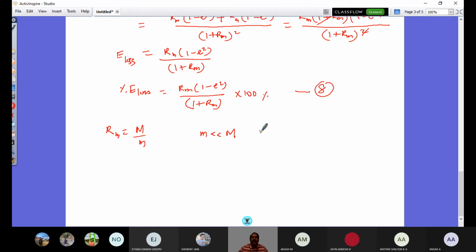If we take this scenario, what would happen to Rm? This is case 1. Rm is very large, since the small ball hits that huge mass. If I assume like that, it's going to be an impact problem, right? So Rm is going to be almost equal to infinity, because the small mass is smaller and smaller compared to this, and you'll have an infinite value. So this general problem then degenerates into a vehicle to rigid barrier impact.